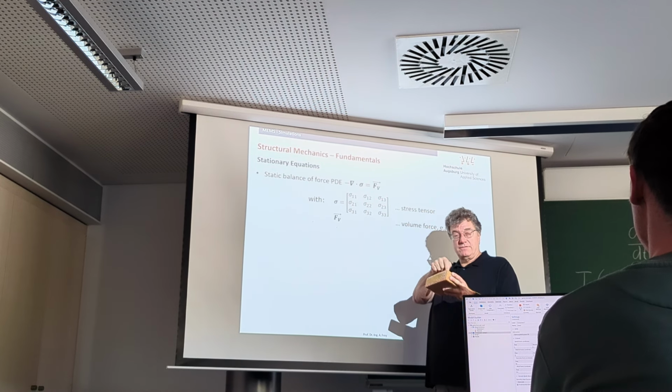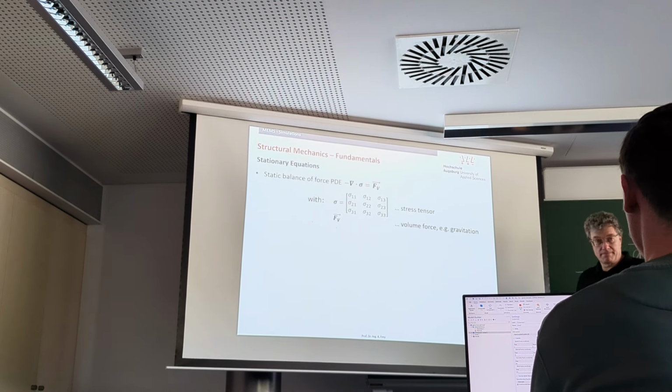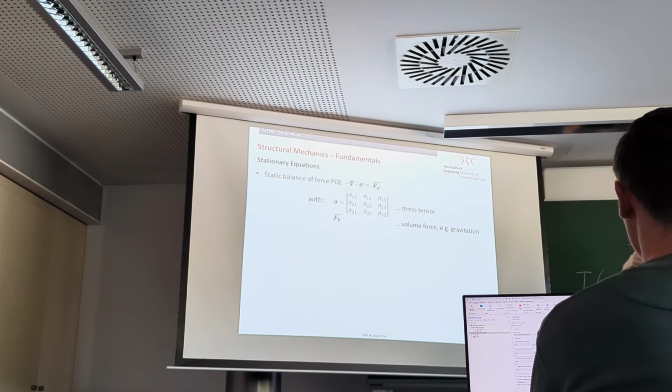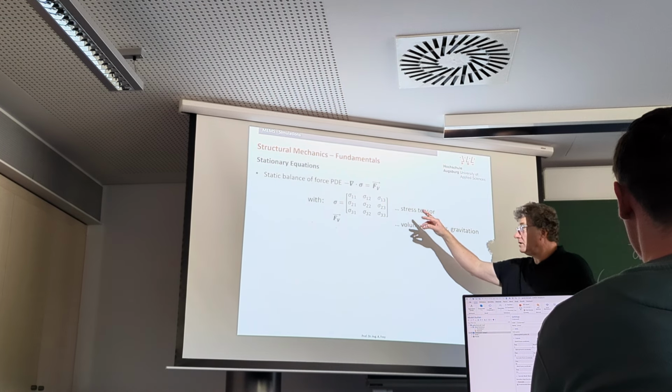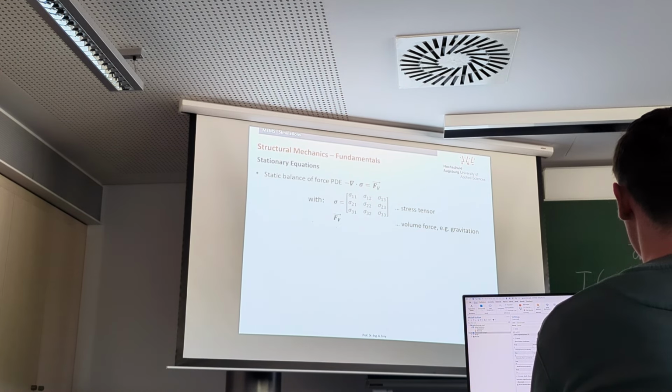The force can be different on every part of that solid. If you start talking about this, you have simple forces like a pressure acting on a surface, then the force is actually equal. But you can have more complicated things, and to have it very general, that is a volume force. That means Newton per cubic meter.